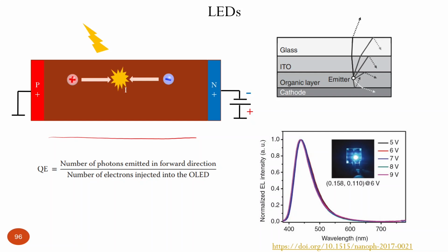It doesn't mean that they will always recombine radiatively. So that's what we should create conditions for in this device. We need to definitely use a very high quality emissive semiconductor layer without traps, because trap-assisted recombination is not radiative recombination. We need band-to-band recombination. So we need to organize conditions when these charge carriers injected from electrodes meet each other and recombine radiatively, and then it will result in some light going out from this area, which we will observe either with eyes or with some detectors, depending on the spectral range, and that will be defined by the band gap of this active layer.